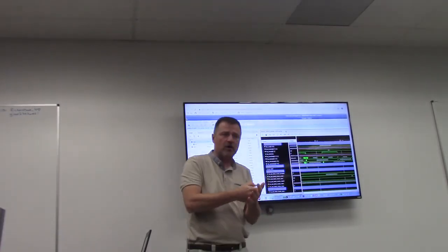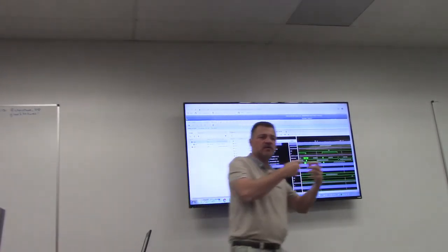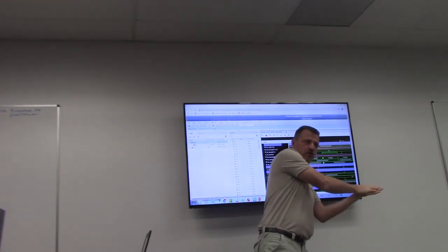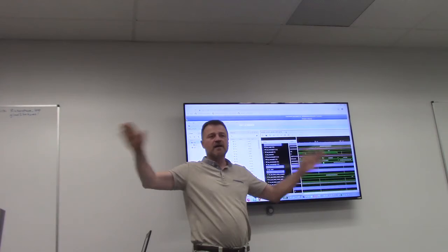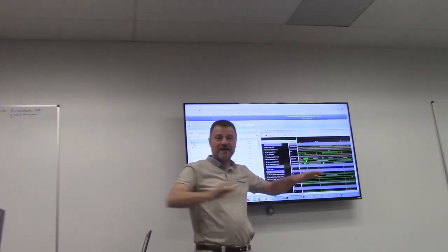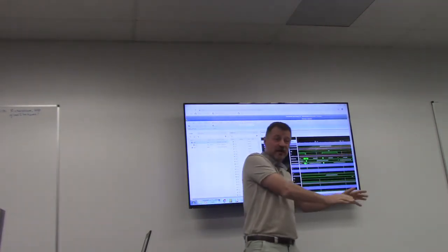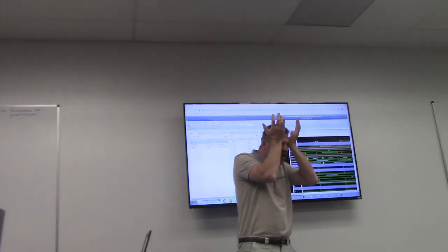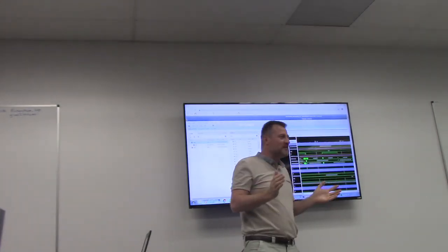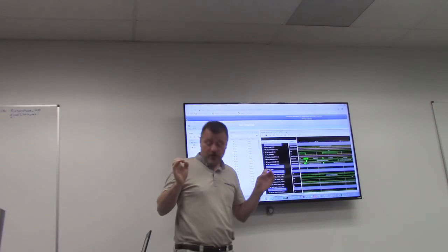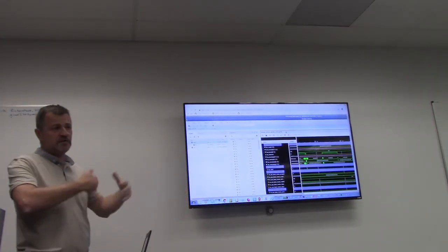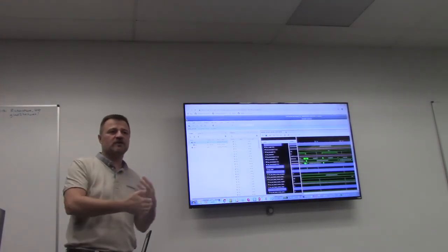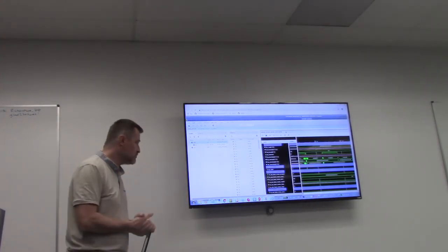When we say clock in hardware, we speak about the FPGA clock, not to be confused with the real-time clock. It's totally different. In hardware we can have several clock domains. When we say that to software people, they say, let's not get into CDCs, it gets crazy. So clock is a source of misunderstanding when we are speaking about this environment which is making a bridge between two domains.